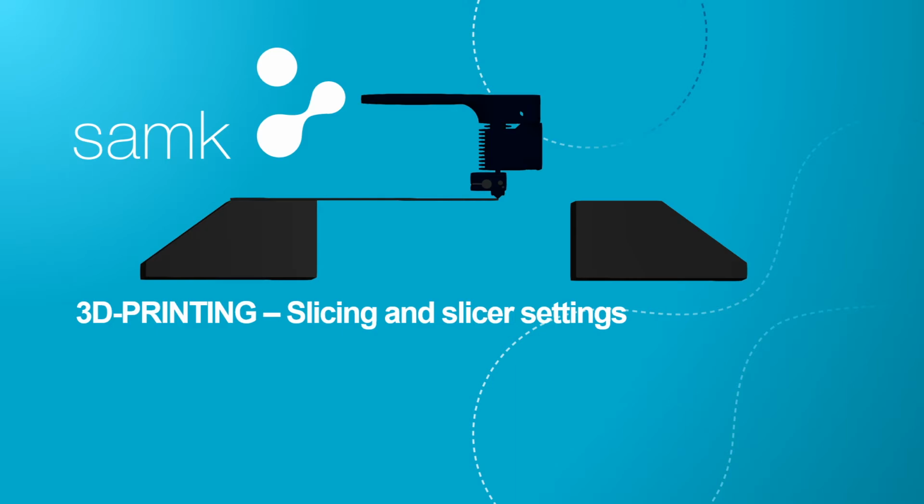Well, what is slicing? Slicing is the step in the 3D printing process in which you create the toolpaths for the 3D printer. You give the slicer software the 3D model of your object, and it will generate the toolpath for the 3D printer itself, where it has to move and extrude how much material, when we're talking about FDM 3D printers. In this talk, we will talk mostly about FDM 3D printers and their slicers.